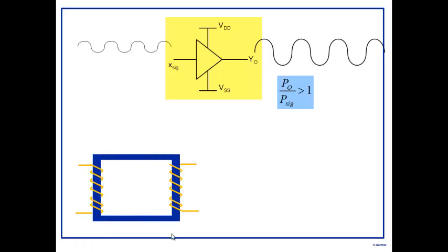Look at this. What is this? A transformer, right? With a transformer, I can get V0 greater than Vin. Can I call it a voltage amplifier? V0 is larger than Vin, right? V0 by Vin, I can get 10, 100. Why? So that's the important point.